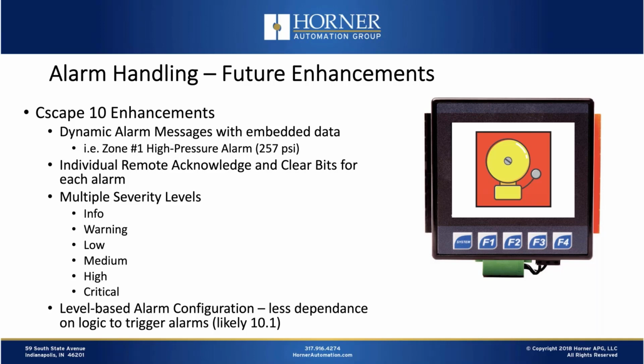One example is dynamic alarm messages with embedded data. So if you remember in my demonstration, I typed in alarm messages like a motor overload bit or over temp zone 1, those sorts of things. Those were fixed messages without any variability to them. You'll have the ability to have dynamic alarm messages that also can have embedded data, one or more data fields in there. So it could be over temp alarm zone 1 with the actual temperature that was captured at the time of the alarm, for instance. So that's a requested feature for sure.